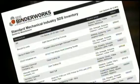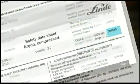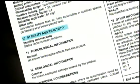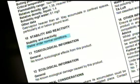That's helpful, but you want more information. There may be other chemicals in the area, and the air temperature changes can be extreme in the local climate. You want to know whether argon is reactive. Go to your company's written hazard communication program. Find the chemical information list. Identify the correct safety data sheet. Skim through the sections until you find Section 10, which is always about stability and reactivity. You can see here that argon is stable under normal conditions. Now you know that it's not normally reactive.